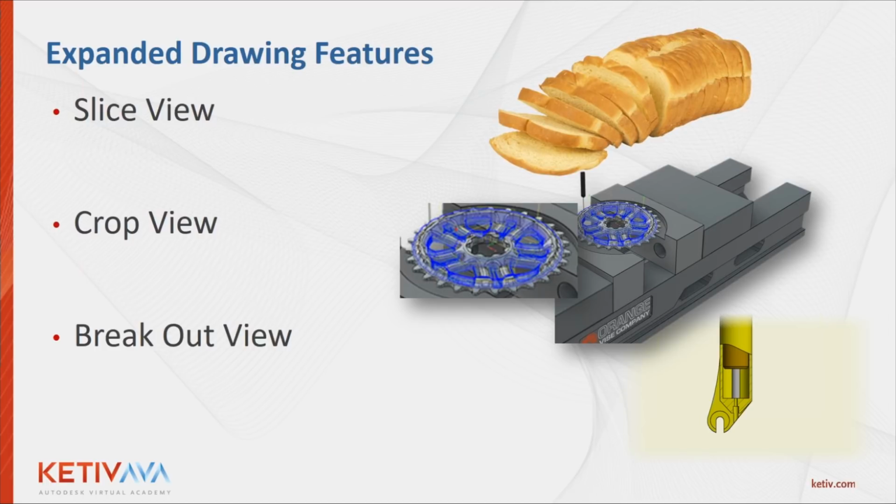Crop views. Crop view can certainly be useful. So if you have a view on a page, whether there's just too much in it or you want to focus in on a specific component, you can certainly use the crop tool to do that.